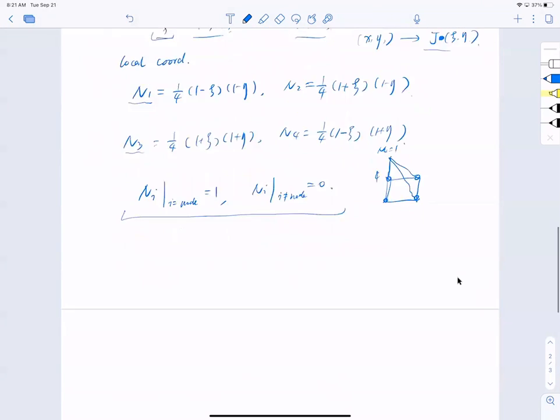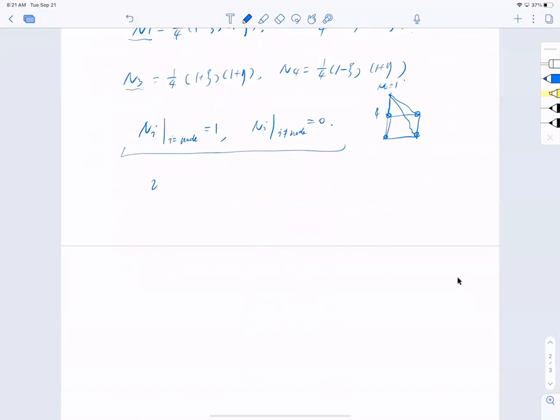So with the shape function, I quickly discretize my field. Now displacement in X direction can be rewritten in terms of the shape function, that is, the sum of Ni times ui. And v equals what? The sum of Ni times vi. So that, ladies and gentlemen, is my linear function. This is not bad at all, right? So now I look at this element, I say, look, I have discretized my element into 4 nodes of displacement.